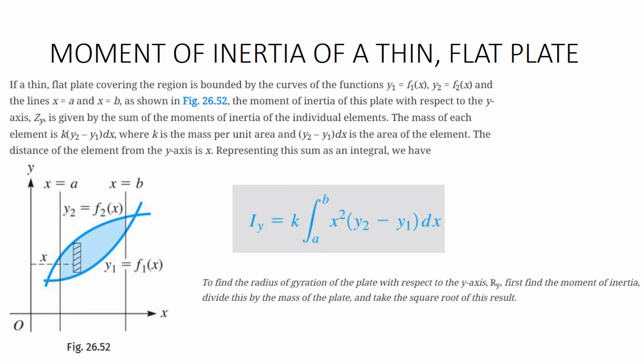Now we've got, let's say, a propeller looking fan blade here in blue, and we want to spin it around the y-axis, and we want to know the moment of inertia, what it's going to take to get that up and spinning. So not counting wind resistance, we need to know the mass of that object and its moment of inertia. So really, I'm going to add up those infinitely thin rectangles that you see shown on top of the light blue area.